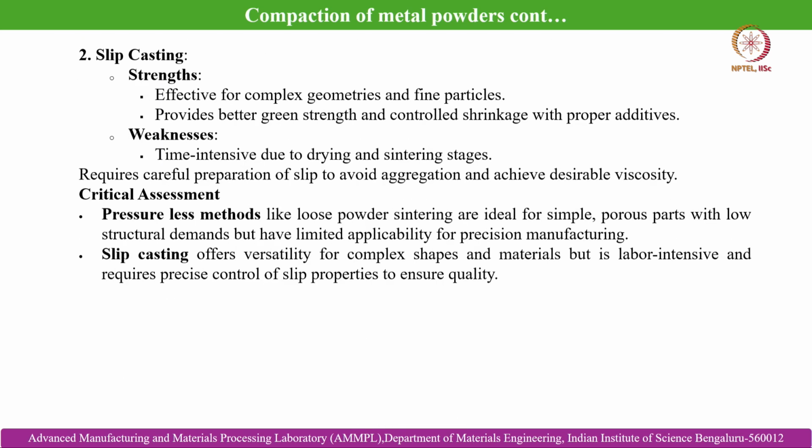Whereas, in case of slip casting, the strengths are that it is effective for complex geometries. It is a much cheaper technique and provides better green strength and controlled shrinkage with proper utilization of additives. And the weaknesses are that it is a time intensive process due to the drying and sintering stages involved. It also requires careful preparation of the slip to avoid aggregation and achieve desirable viscosity of the powder solvent mixture.